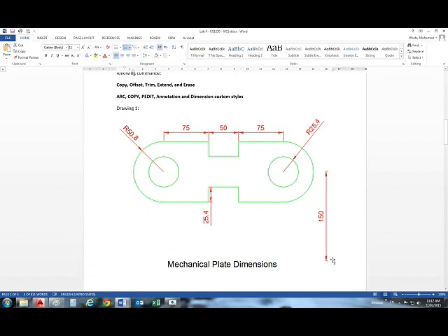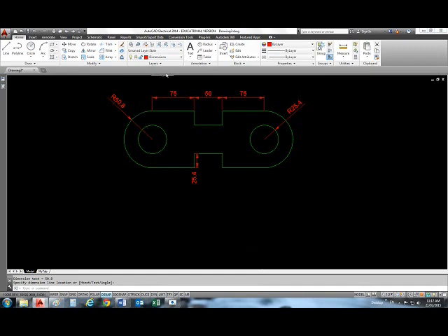It needs to be 150 millimeters below the center. Needs to be centered. So let's put some temporary guidelines. I'm going to go to layer 0 or even def points. Be careful with def points. Any objects placed on def points layer will not print. You'll be able to see them on screen, but they will not print.